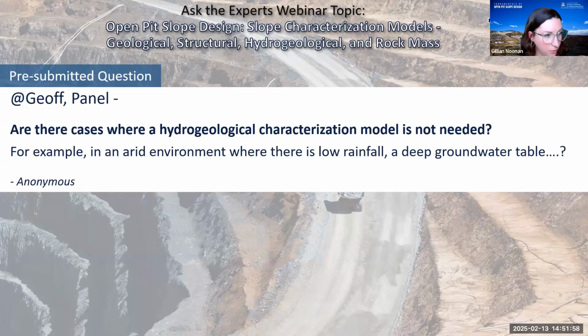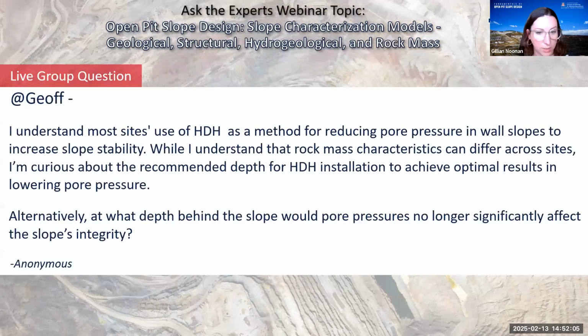And then also, while I have you, Jeff, I'm going to pull up one more hydro-related question that came in from our live group. I know Blair Douglas covered the operational hydrogeology in the course, but this is well within your realm of expertise as well. So maybe you could just quickly comment on horizontal drain holes and the recommended depth for installation to achieve optimal results. And then is there a depth behind the slope where pore pressures would no longer significantly affect the integrity of a slope?